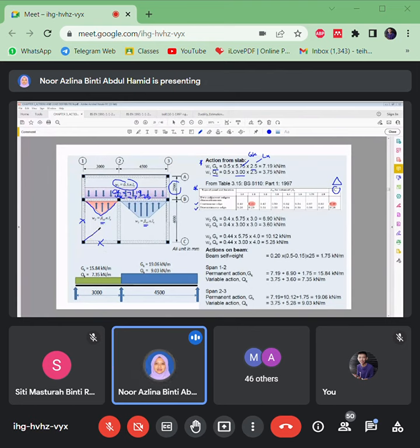Remember, we also have another triangle, right? But this one is discontinuous. At the same time, we also need to ignore this side because we focus on this beam. So that's why this triangle is a continuous edge. So take the continuous edge, 0.4. So this is BVY for panel 2. Okay, 0.4 is its coefficient, multiplied by GK and then multiplied by its short length Lx.